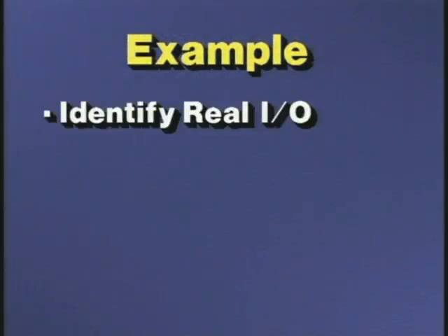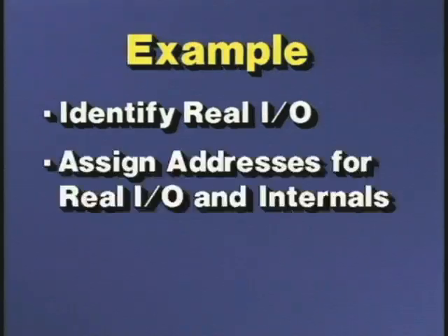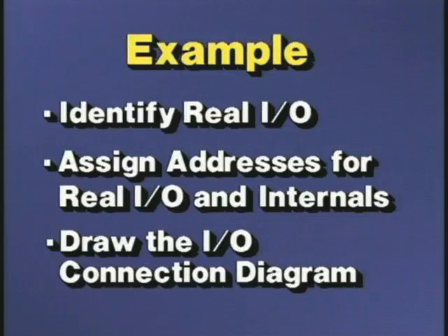Let's briefly look at an example which will show us how simple it is to identify the real I/O field devices which can be connected to the PLC. Then we'll assign the input and output addresses for real and internals, and finally, we'll draw the I/O connection diagram of the identified field I/O.